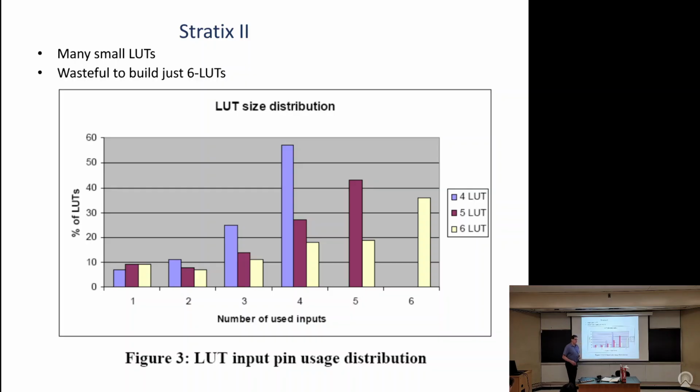And you have to tell the synthesis flow in an FPGA CAD tool. I already kind of showed it to you, but the first part looks a lot like ASICs: recognize what the HDL means, that's called elaboration, so you turn things into basic structures. Then optimize the gates, which just means you might figure out, oh, I could turn these two AND gates into an OR gate, that's better. So that also looks like ASICs. The next step is called technology mapping. That's different. You map to lookup tables, kind of like a bin packing problem.